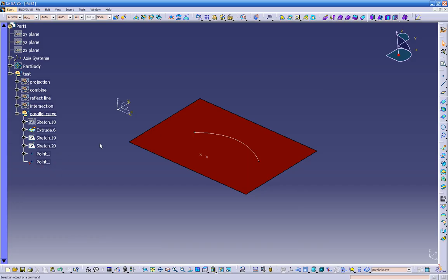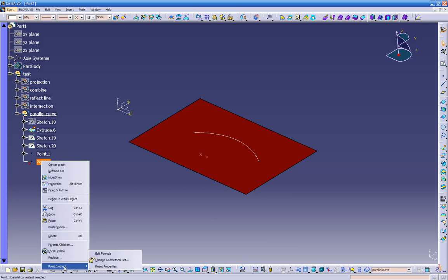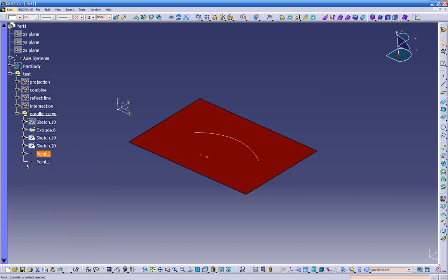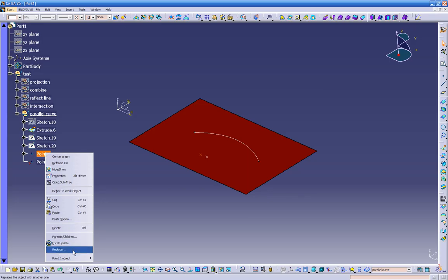So that's why, when I build my geometry, I want to make sure that everything is linked together, because if I don't like something, I can just click on my sketch, edit it, and then automatically it's going to update my model. But once you break the link, we're going to have a little bit of problems. So for right now, to break the link, it's very easy. You do a right click and you go isolate.